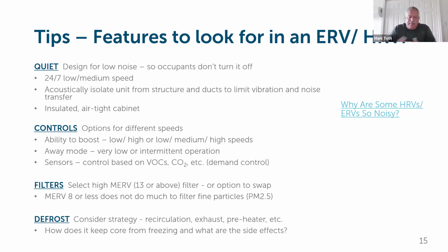So just to say, if you're looking at CO2, CO2 is a great way to control areas that have a high concentration of people. Say if you had a big home and someone was building a home that they were going to have an exercise room, or a room where they're going to have people over all the time to hang out and do projects or whatever it's going to be, or it's a meeting room, that kind of environment, CO2 is great because you're going to get CO2 spikes and you're going to ventilate it.